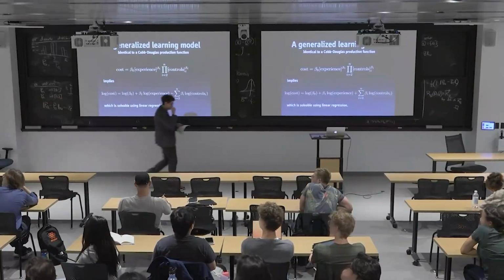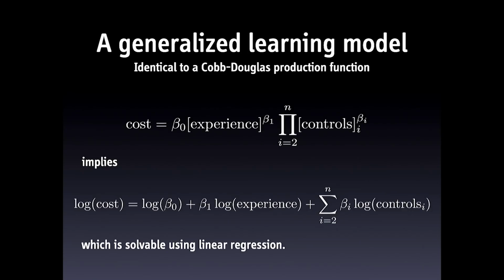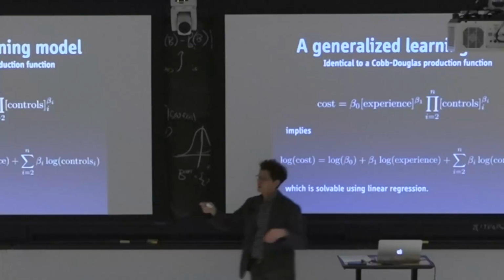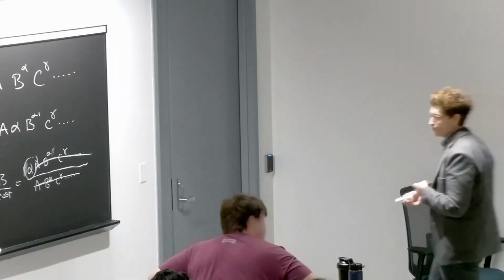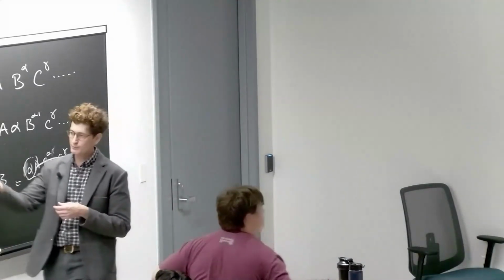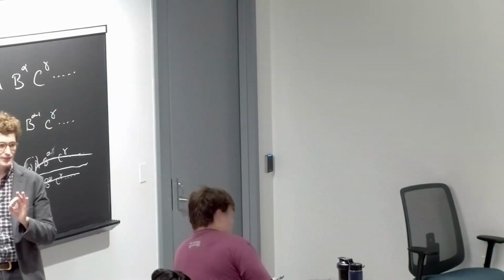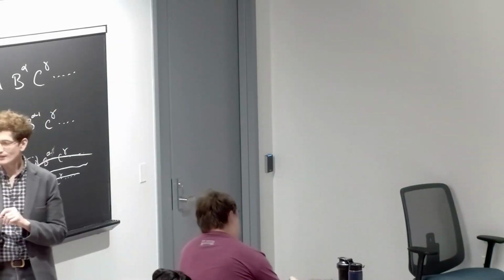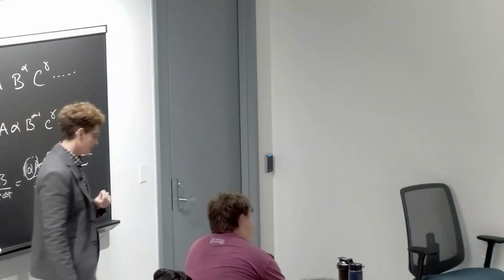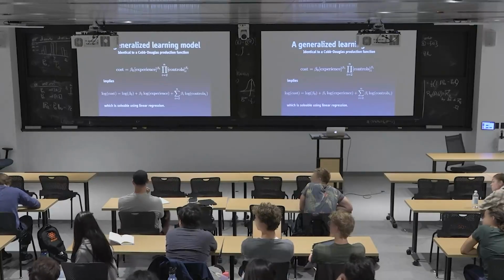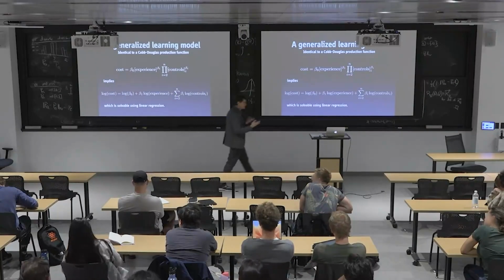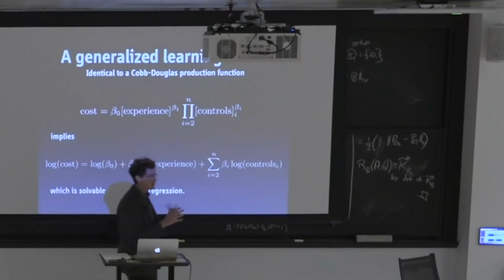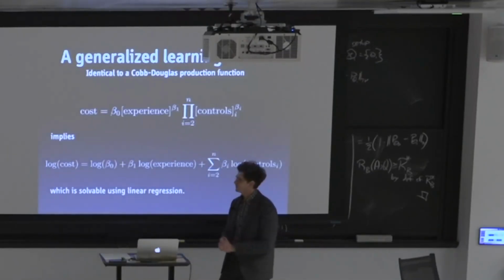So what does that mean? How do we interpret that? It means that a 1% change in the cost of some input B will have an alpha percent change, a constant effective percent change, in the cost of the reactor. That idea of a constant percent-for-percent change is a nice assumption that seems to more or less hold and is sort of independent of scale. And so this is why people use this type of model.